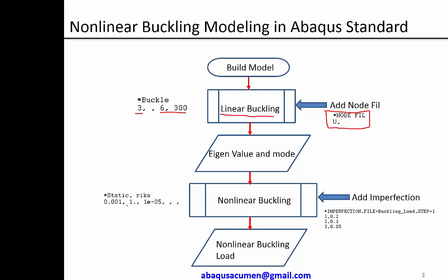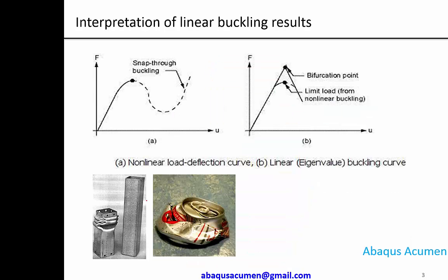And then we are going to capture the post buckling behavior. To get the post buckling behavior in Abaqus you have the arc length method, and we are going to use the Riks method. So this will be the learning part. Along with imperfection you have this snap through behavior and the Riks method.